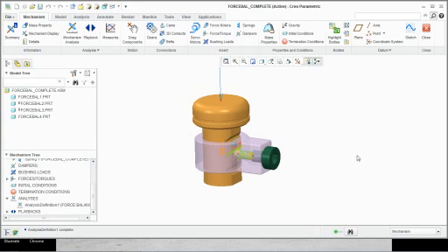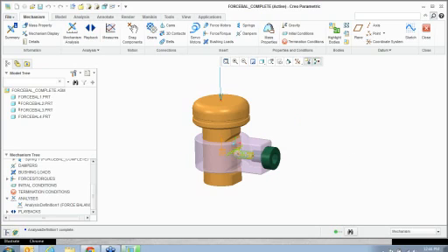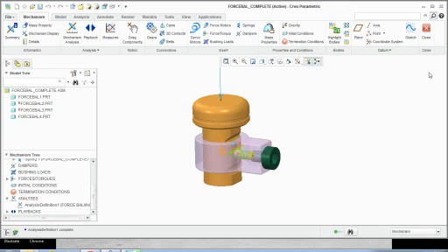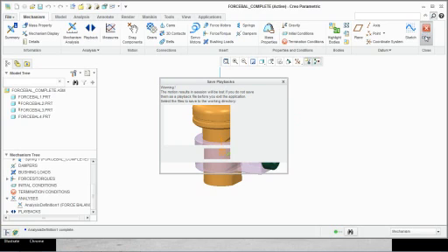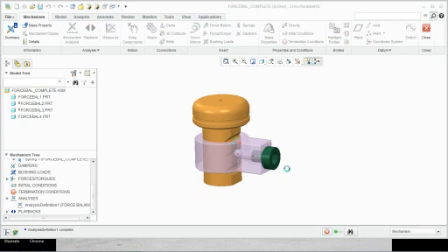Or say, I have a little loader that's carrying a bunch of grain. Then I have to hold it at a 45-degree angle. Now my piston cylinder is stretched. If I have to hold it over there for so much weight, what is the amount of liquid pressure or oil pressure that I need to apply to keep it in position? Those kinds of things are generally done using the force balance analysis. So typically you create a load cell so that it tells you at what point you need to apply what kind of load to stop this mechanism from moving.